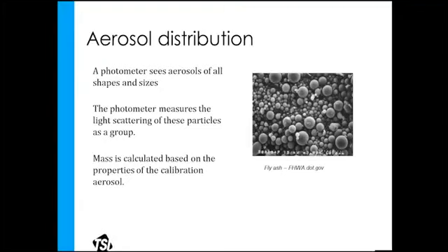And since we don't know what that aerosol is, that's why this instrument will never be that OSHA method to verify compliance for respirable silica or for hexavalent chrome and welding fume. It doesn't know what aerosol it's counting. It's, here's the bucket of balls. You want to tell me how much a bucket of balls weighs? Here's how much the bucket of balls weighs. I don't know what kind of balls are in there. So if you've calibrated your aerosol to weigh this much, here's my mixture of ping pong balls, golf balls, tennis balls, here's how much it weighs, tell the instrument that, now it's going to be more accurate.